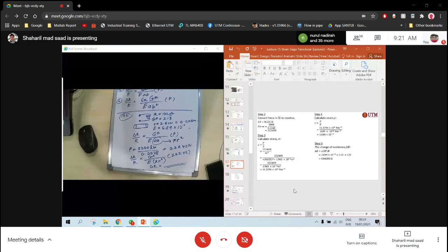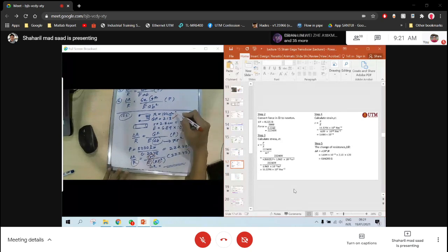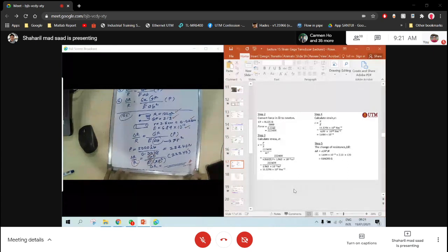Because already you have your GF, your strain gauge factor, the Young's modulus of the rod, pi r squared, R is there, P done, R the initial value for the resistor, done. Then you can get the delta R.